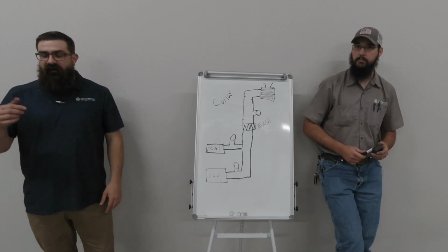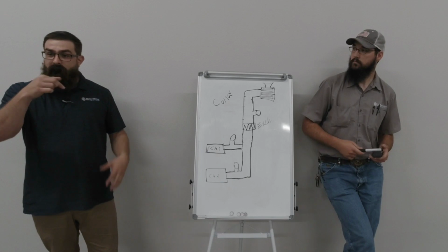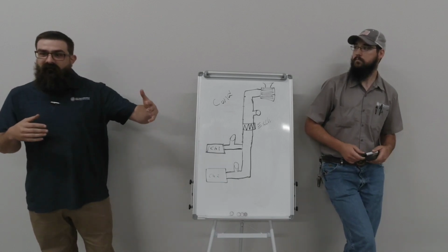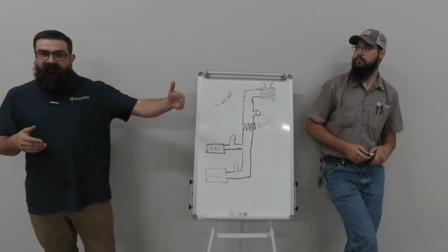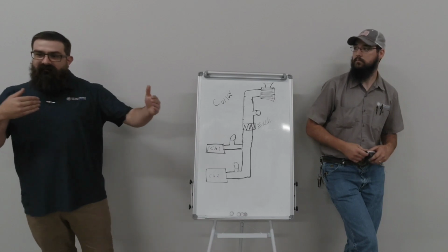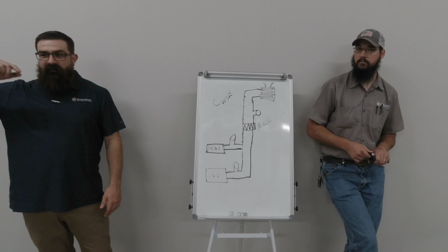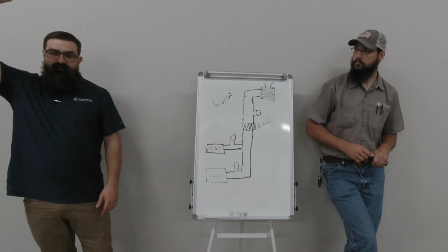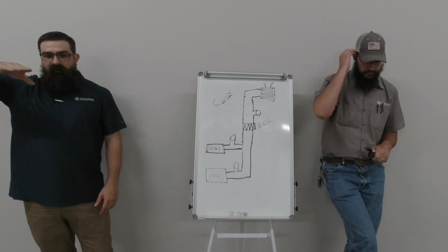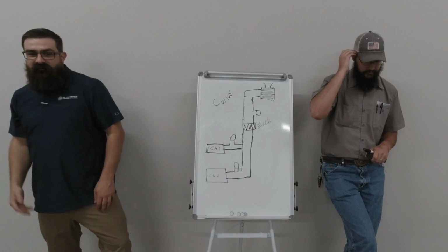That's why we always put our pressure sensors in the middle of the ductwork, or 3/4 of the length down. You don't want them right at the beginning, you don't want them right at the end, because you need to be able to see that entire range. It's the same thing with pressure. That's why a lot of buildings will have multiple pressure differential sensors, one at the top, one in the middle, depending on how the system's configured.